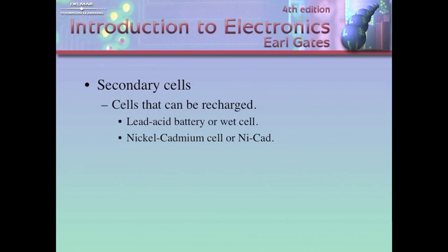Like the car battery, you open the... The vent? Yeah. You can fill them up, right? Yeah, you need to make sure that you maintain the water level inside, because it's a water-acid solution that is the electrolyte solution. So if that value goes down, then the battery's not going to be able to hold a full charge. So a lot of times I thought my battery was failing, and I open it up and it's just down on water. You can just add distilled water. Make sure you add distilled water. By adding tap water, it's got chemicals in it and minerals, and it can cause the chemistry to go strange.